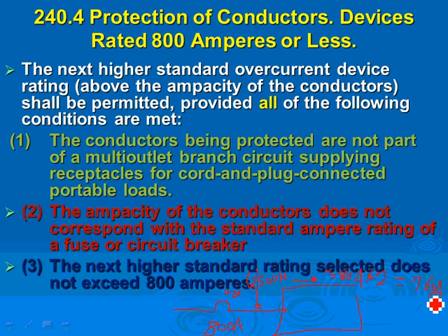800. So that will allow you guys to have conductors protected by an overcurrent protection device where the conductor is slightly less than what the overcurrent protection device is rated for. Now once you hit that ceiling called 800 amp, then you start matching your conductor to the overcurrent protection device. Example, a 1000 amp circuit breaker. You have to land 1,000 amps worth of cable or more. That's it. So a lot of contractors love to take advantage of these rules.